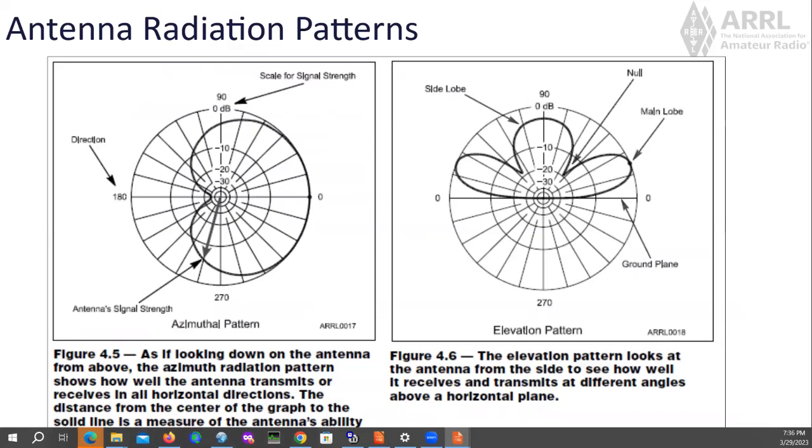And so you're not usually all that interested in how much up you're getting with your antenna, because that's probably going to go right on out into space. The horizontal is what you're really interested in, because if you're wanting to talk to George across town, then you want to point your antenna where your maximum signal is in his direction.